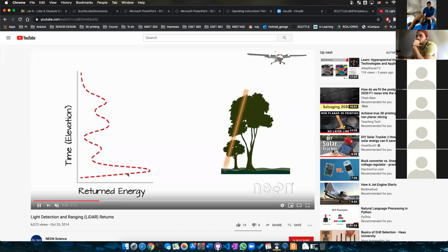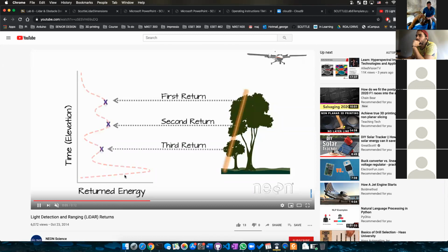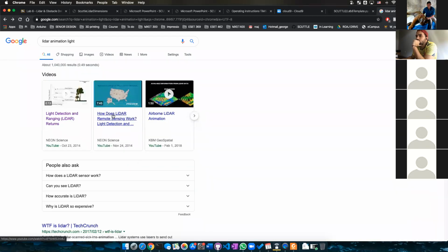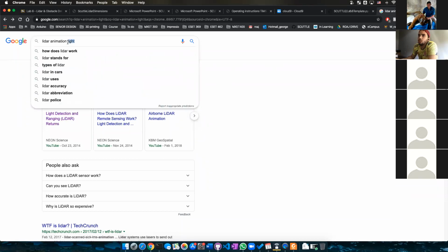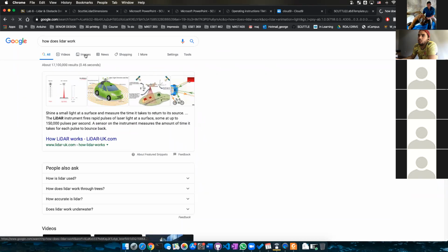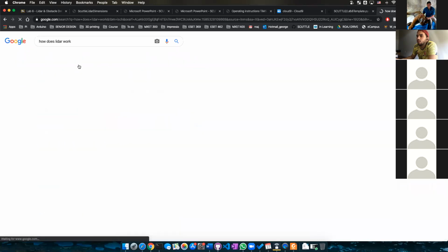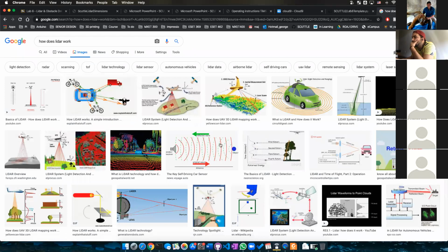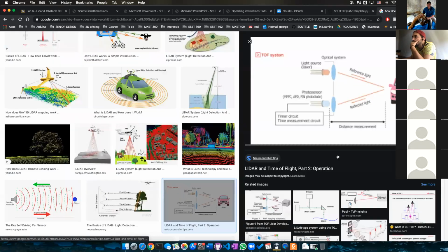Okay, I'll let Jorge work at that. But basically what it does is inside of the LiDAR, there's a spinning, actually it's not a spinning laser, it's a mirror that spins, and there's a laser at the bottom that's pointing up at the mirror. As that laser spins, it pulses. And what happens is like this, look. That's basically it. And it just measures how long it takes.